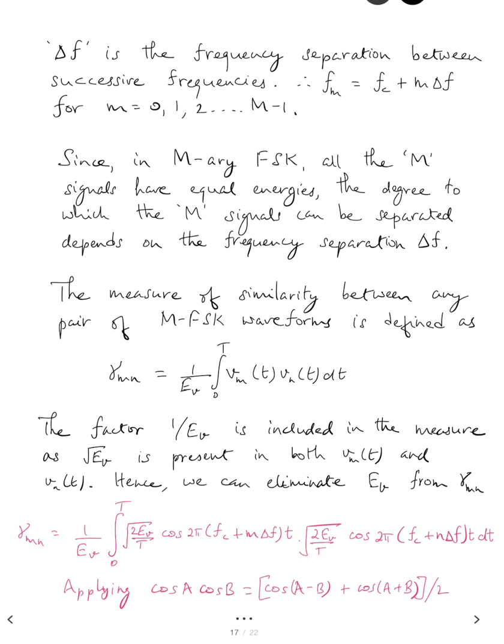How do we find the separation, the delta f, which will make the carrier signals orthogonal with respect to each other? But remember, the orthogonality that we are achieving here is in the frequency domain, because we are choosing appropriate frequencies that will make the same carrier signal orthogonal, right? It's the same cosine 2 pi ft, but we are choosing f to be different values such that the two values become orthogonal to each other.